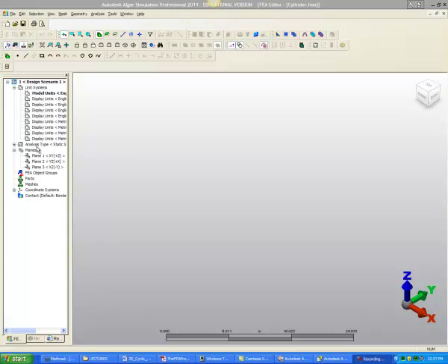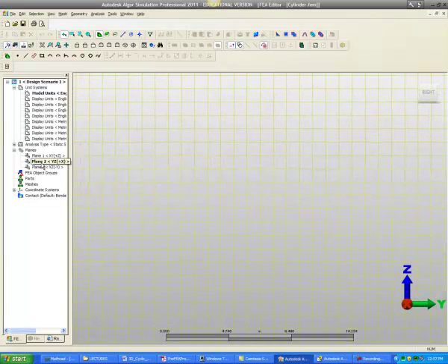axisymmetric problem. Now you'll remember for a problem to be in 2D, it has to be in the YZ plane. So putting it here in the YZ plane. Okay, next thing. You have to set it up so that the axis of symmetry is in the Z direction. Okay, and remember I said if it's solid, then your cross-section will start at Z equals 0. If it's not solid, your cross-section is not going to start there. So let me just show you real quick what I mean.